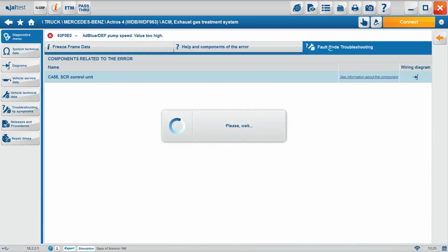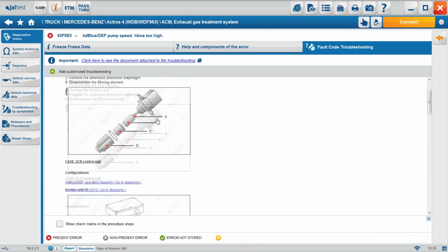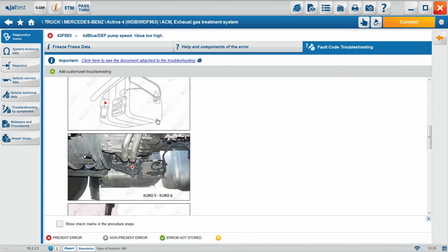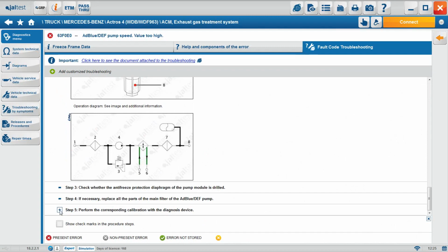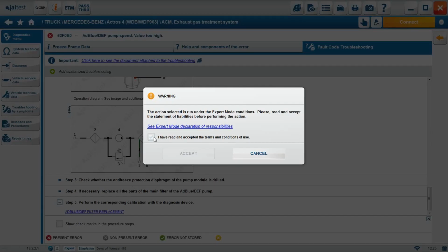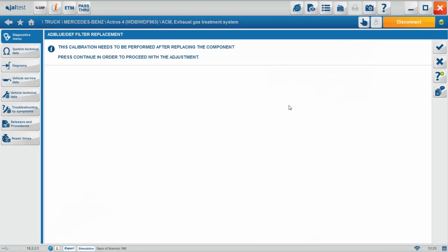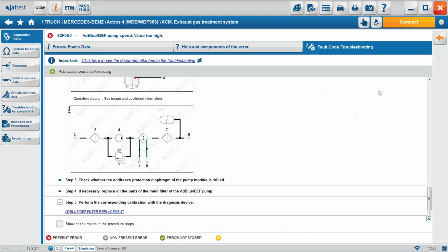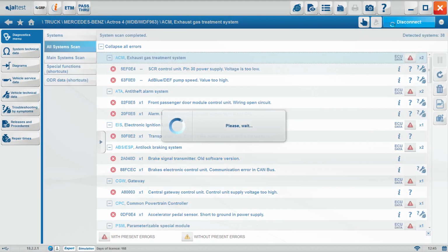On many occasions, a troubleshooting of the DTC is available, where a step-by-step process can be followed to solve the DTC. Internet connection is required to display the troubleshooting. Among all the steps, many hyperlinks can be found. They are linked to diagrams, more technical information, or even diagnosis tests. Straightforward information to save time while solving a problem.